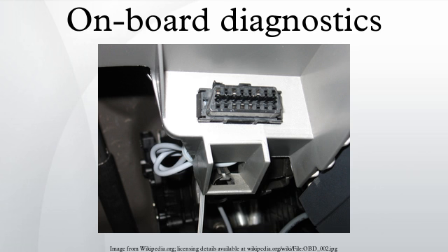For a 1994 Corvette the implemented OBDI codes are P0116, P0118, P0131, P0135, P0151, P0155, P0158, P0160, P0161, P0171, P0175, P0420, P1114, P1115, P1133, P1153 and P1158.